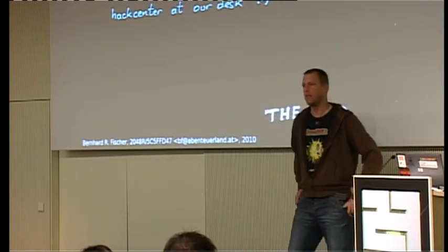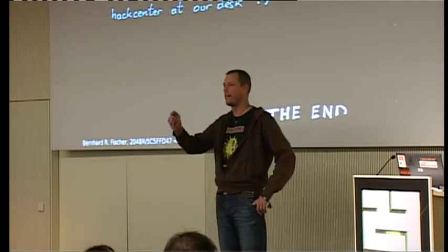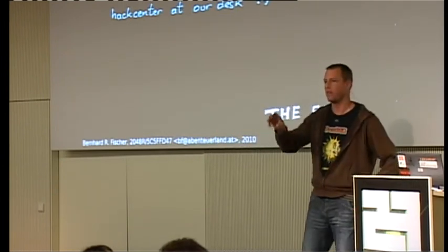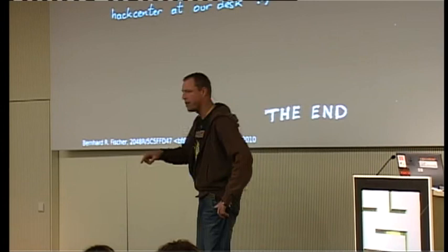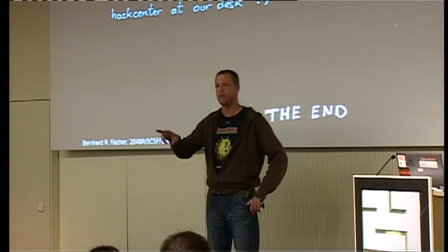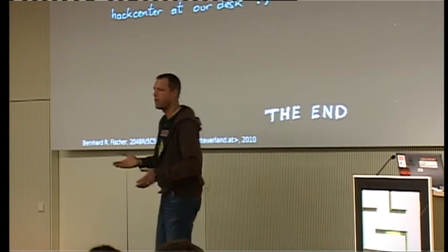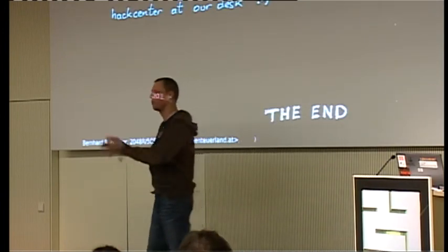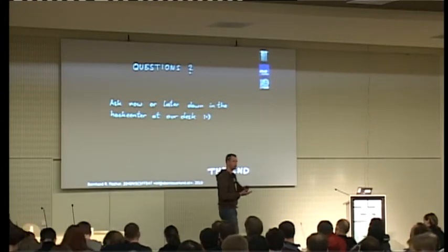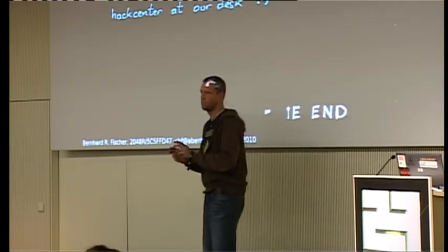Yes, there is a problem. First, you should never trust the elevation data that you get from your GPS device. It's completely unreliable. So we should not trust at least the elevation. Referring to the coordinates, the latitude and the longitude, if you have a new modern device, I think it's accurate enough. Because if you're somewhere in the middle of the sea, you usually have very good reception. You see all satellites, so it's pretty much accurate.